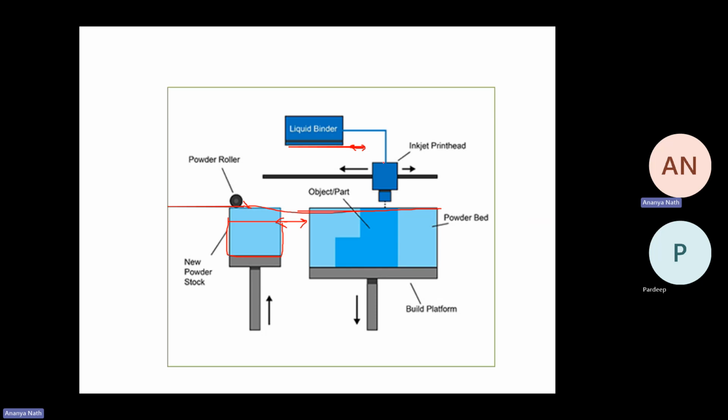So the powders are spread on top of the build plate. The binder is coming. So basically the glue is coming. Glue is falling over the build plate on the powder wherever it needs to be joined. It needs to print the part, and layer by layer this process is happening, and we are basically gluing the powder together. If you remember from childhood crafts classes, we used to put glue and then put glitter on it and then just blow out all the glitter, and you'll have the perfectly shaped glitter you have drawn over a picture on the paper. Similar case, just the opposite process.